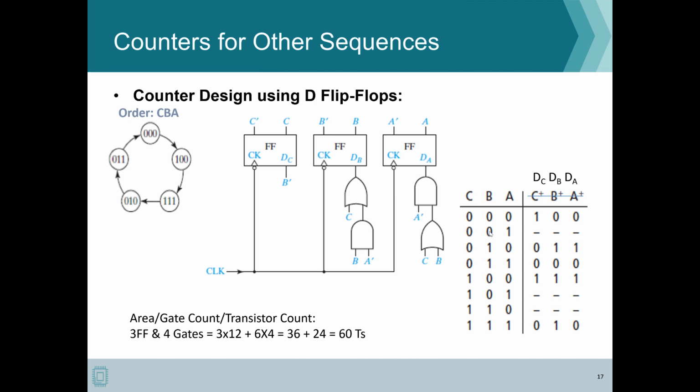So now we're going to see a sequence of the same example, which is a modulo 5 counter, and we are going to see how you can perform these using the D flip-flop, the SR flip-flop, and the JK flip-flop. So you're going to see the same example performed across all 4 types of flip-flops. So here we have, as you can see, this is our current state, this is our next state, and we have actually included don't cares.